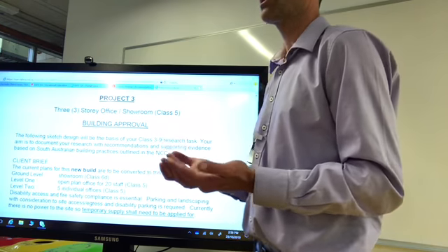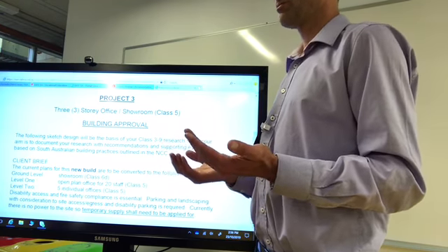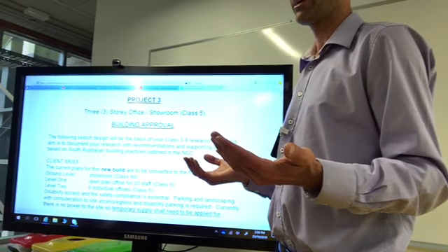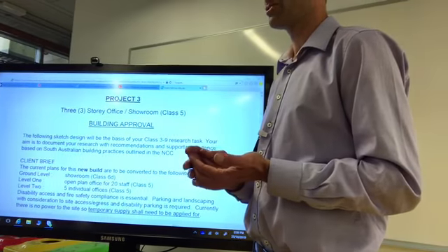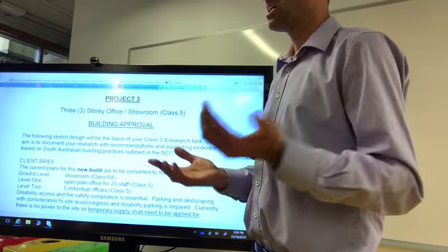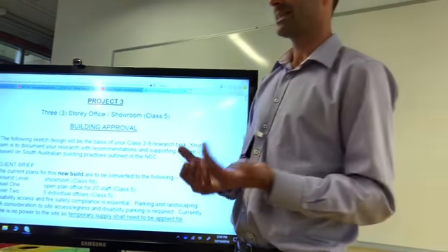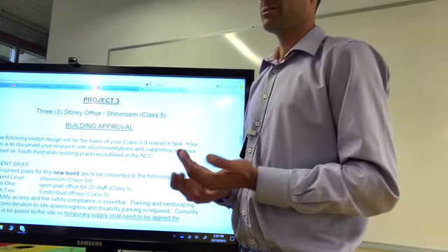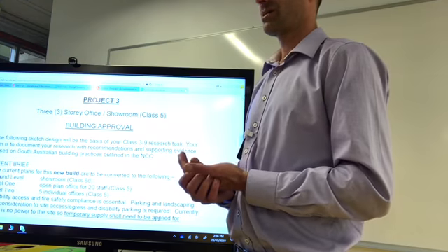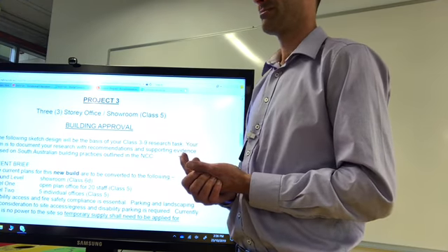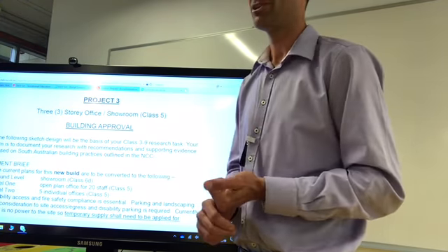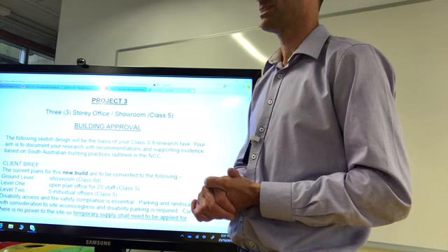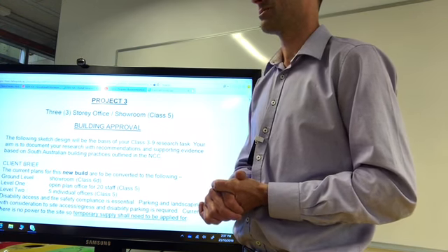I'd say, look, as long as the installation of the waterproofing membrane has been done correctly and you follow the manufacturer's instructions with that waterproofing membrane, I think it's less likely to fail than your box gutters. Box gutters are kind of renowned for their failure, and there are many issues that come about with box gutters. So in terms of failure, that's the most likely one to have issues with.